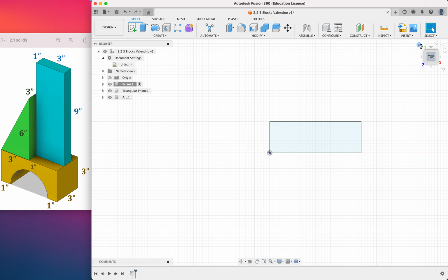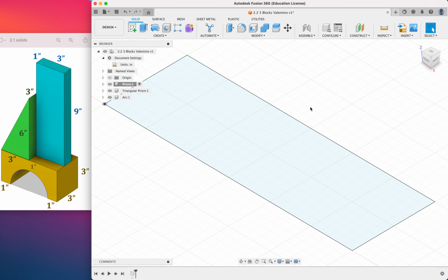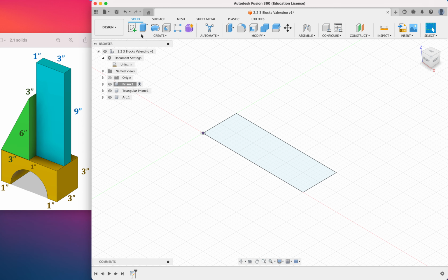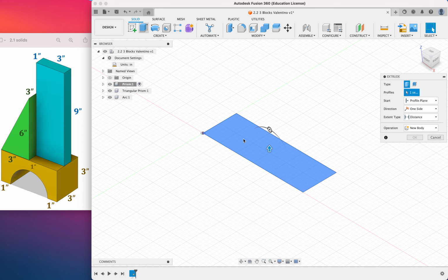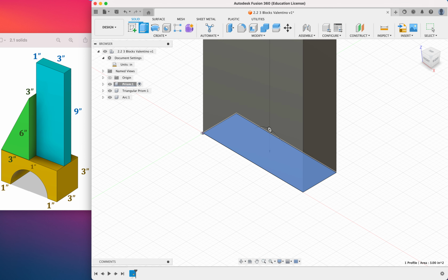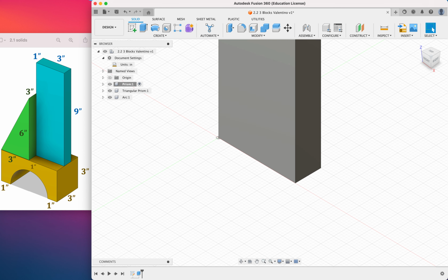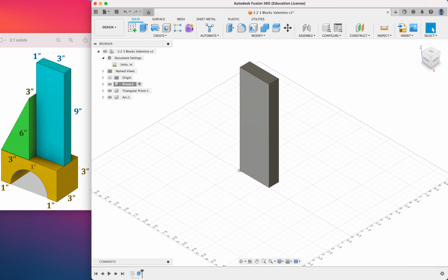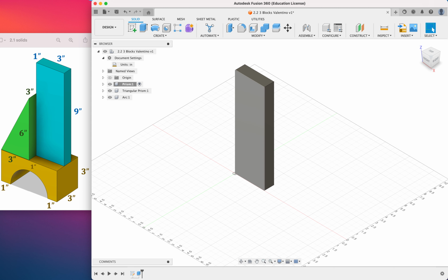I'm going to hit my Home button. All right, I'm going to pinch out. So now I've got my figure right here, and now I hit Extrude. How high does it go? It goes 9 inches. So I hit the number 9, and I hit Enter. When I pinch out, I notice the figure looks like this. Hopefully you have a similar figure. Now you may say, wait, it's going off my grid. Well, that's okay. The grid is constantly expanding. There really is no grid.